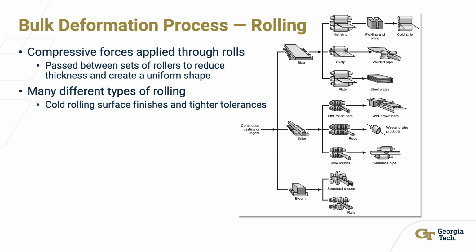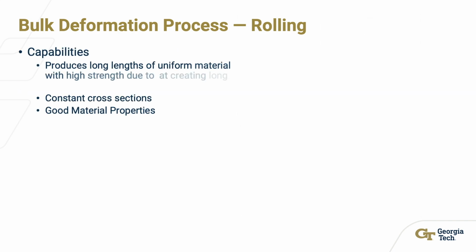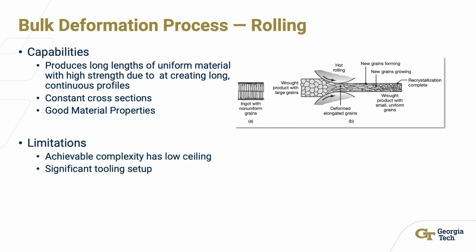This is an effective method to reduce grain size and refine the microstructure in metals, resulting in improved strength and good ductility. In this process, cast structures of ingots or continuous castings are converted to a wrought structure, as seen in the diagram. However, rolling does require substantial equipment and infrastructure and is very ineffective for creating highly complex shapes.